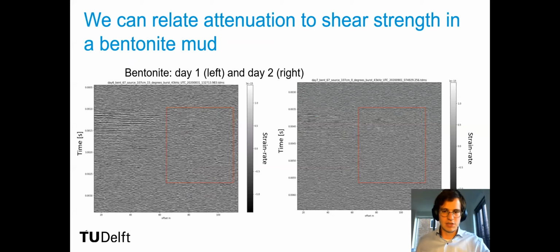In particular, we're interested in looking at seismic waves for characterizing the subsurface. And we see, in a similar way that Zack explained, quite a wide variety of phenomena, including ocean waves at low frequencies. Here's the same plot, but on log and linear scales. On the linear scale, we can see that above about 0.3 hertz, the recorded DAS strain record is dominated by Scholte waves and potentially other seismic modes. At the lower frequency end, we see microseism that can be quantitatively associated with the ocean waves.